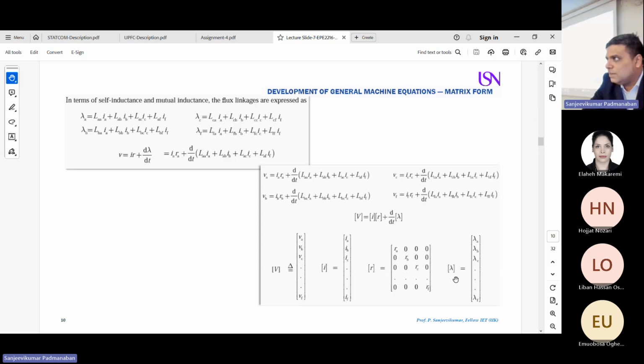Then what is delta? Flux linkages are very important here. So we take it as a one column matrix, which has all the three phase flux linkages and, of course, the field excitation. Is it clear to you? Now I model my complete electrical machine into 4 matrices. If I know the values of the resistances of the 3 phases, the voltages and the currents, I can easily model the system in my software and analyze it without going into real time.